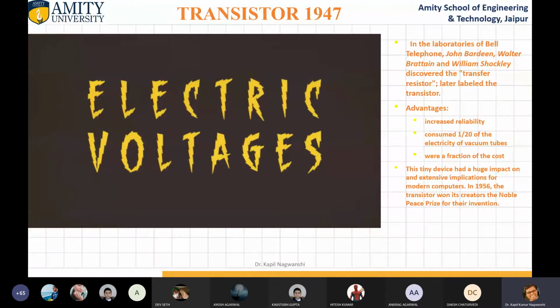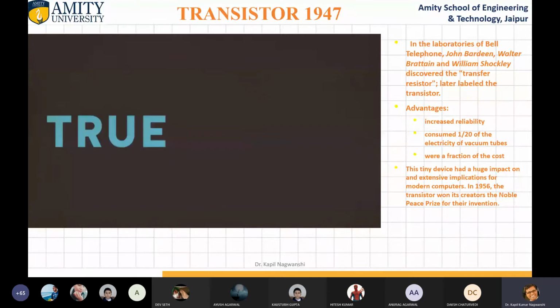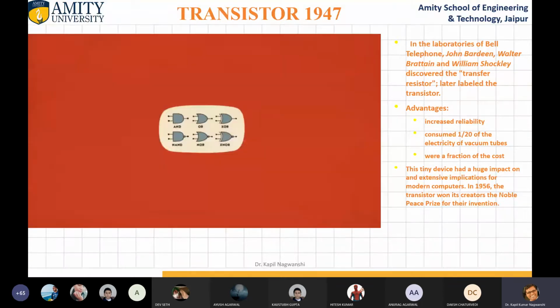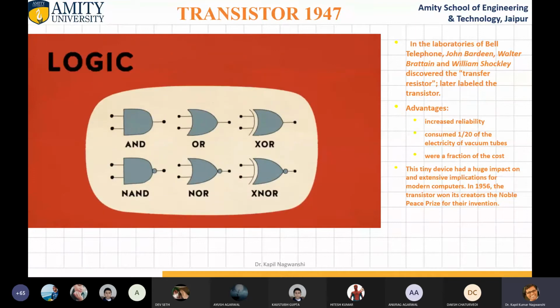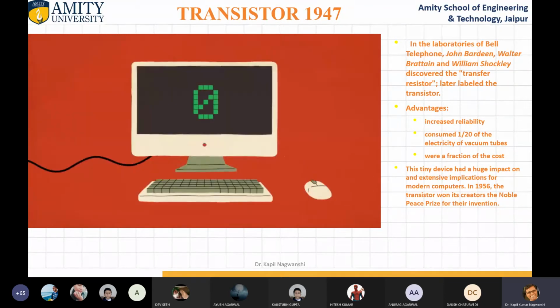Most such computers use a type of math called Boolean logic that has only two possible values, the logical conditions true and false, denoted by binary digits 1 and 0. They are represented by high and low voltages. Equations are implemented via logic gate circuits that produce an output of 1 or 0 based on whether the inputs satisfy a certain logical statement.